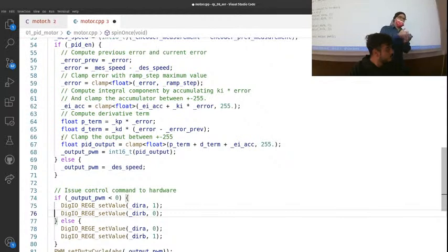Because of the braking coefficient, once the tire is locked, the tire tends to skid. Until you have grip, you manage to hold something. Once you start sliding, there is this effect that you might slide even further. The ABS acts on your braking to prevent that. We can do it, but not on this robot. We might need an IMU, and then you can do the ABS, or you can do a traction control.